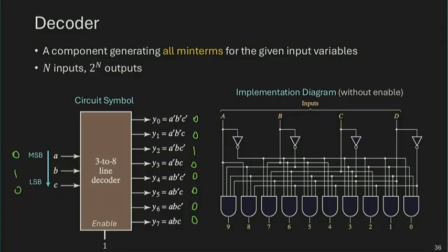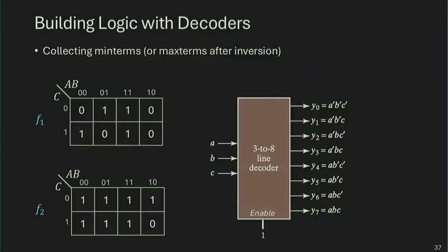And again, this is just a function. And if you really want, you can implement that using some combinational logic, using AND gates, some inverters. So 1, 1, 1 will make the last output a 1, and this one is actually a larger 4-bit decoder implementation. And you can use decoder to build function. Decoder essentially gives you a bunch of minterms. Because, let's say y2 is 1 only if input represents 0, 1, 0.